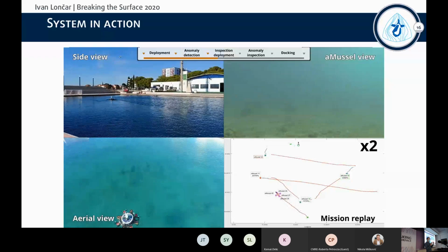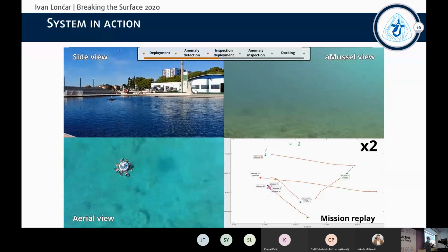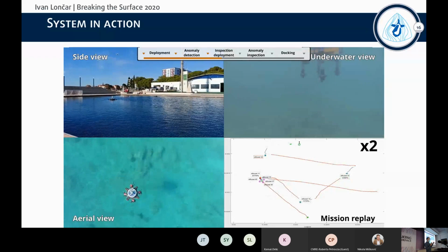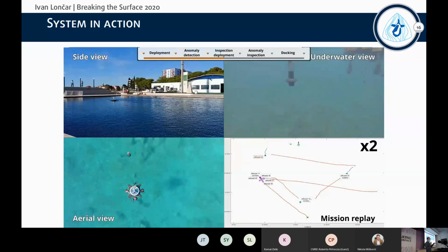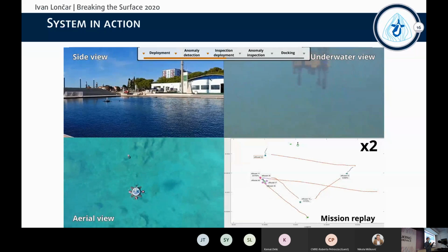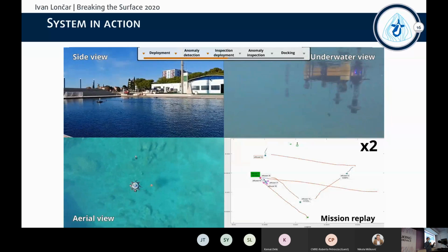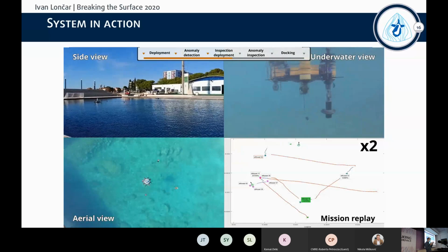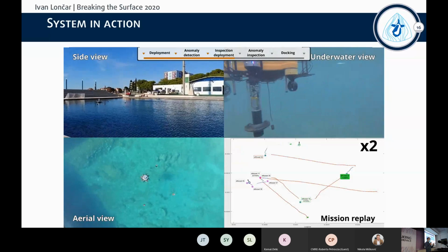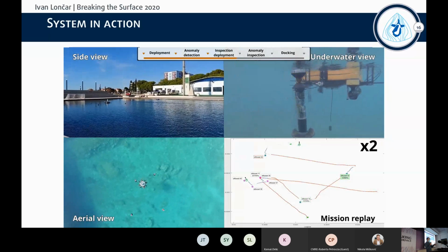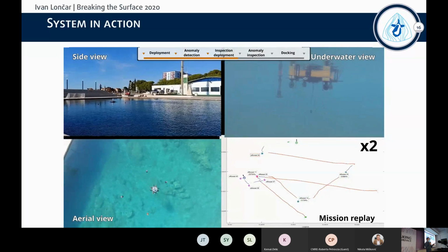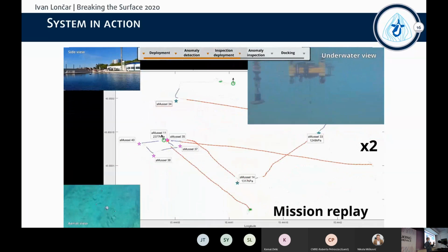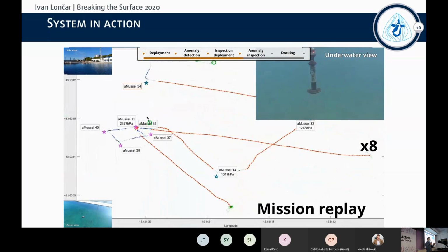They don't know when the signal was sent, but if we take into account that they received those acoustic signals at some points in time, and we know the difference between when the anchors broadcast those signals, we can get basically time differences of arrival and differences in ranges between the multiple anchors, if I explained it well.